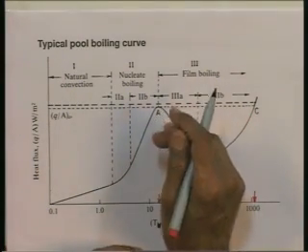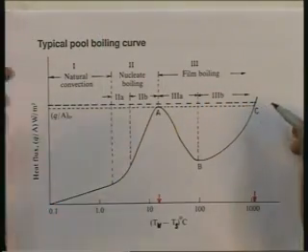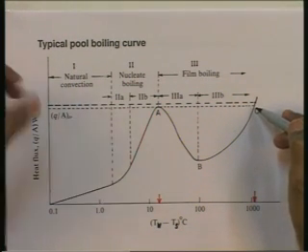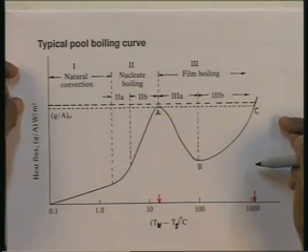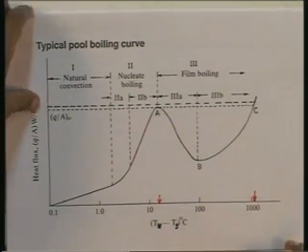And in practice, wherever heat flux is the controlling factor, and it is in many situations, it is important not to exceed this value, in order to see that the wall temperature does not go above some safe value and does not get damaged. So, that is why it is important that this point be known and the value of critical heat flux be known.